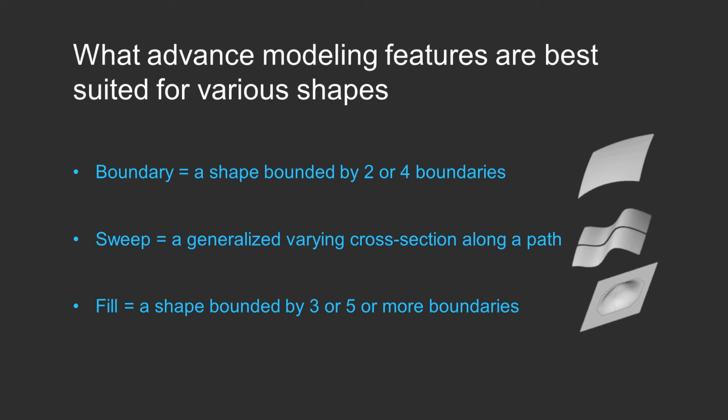If the line were curved or a spline, it would be that profile sweeping through that nonlinear path. By adding more paths, or what we call guide curves, you can constrain the profile to change as it goes along the path, and that makes for a very powerful feature.